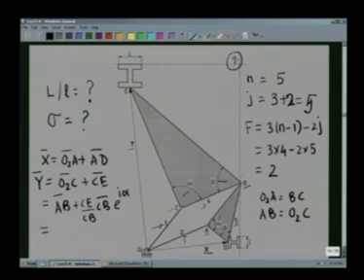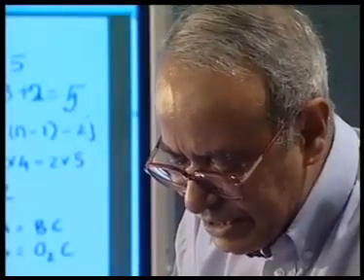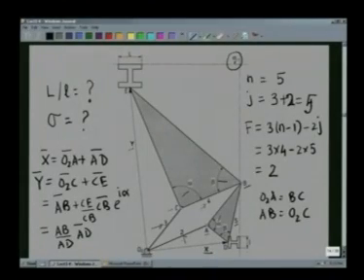Now, vector AB I can write in terms of vector AD exactly the same way. I write the magnitude has been magnified by AB by AD and the vector AD, and the vector AB is at an angle alpha in the counterclockwise direction from the vector AD. So, I multiply this by e to the power i alpha plus this term. So, I have the vector y as AB by AD into vector AD e to the power i alpha plus CE by CB into vector CB e to the power i alpha.